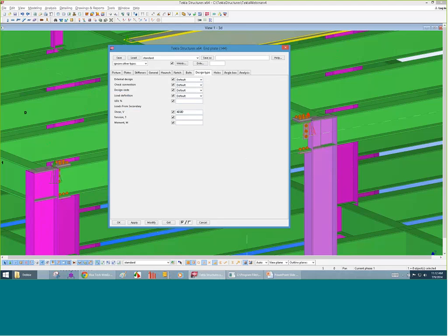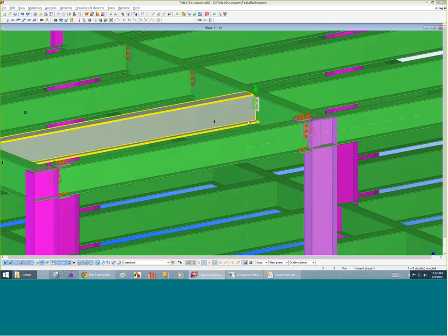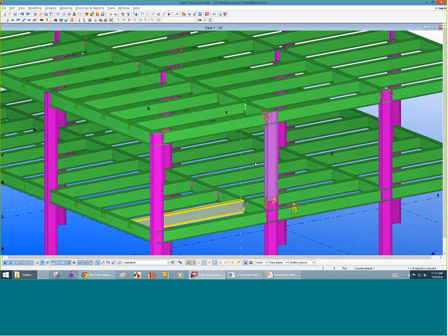So this is just an end plate. I'm just going to apply some shear. I put 40 kips listed here, and this is going to be sent directly over to RISAConnection. So I'm going to say OK, and I can double check. Let's look at a couple other connection types here.